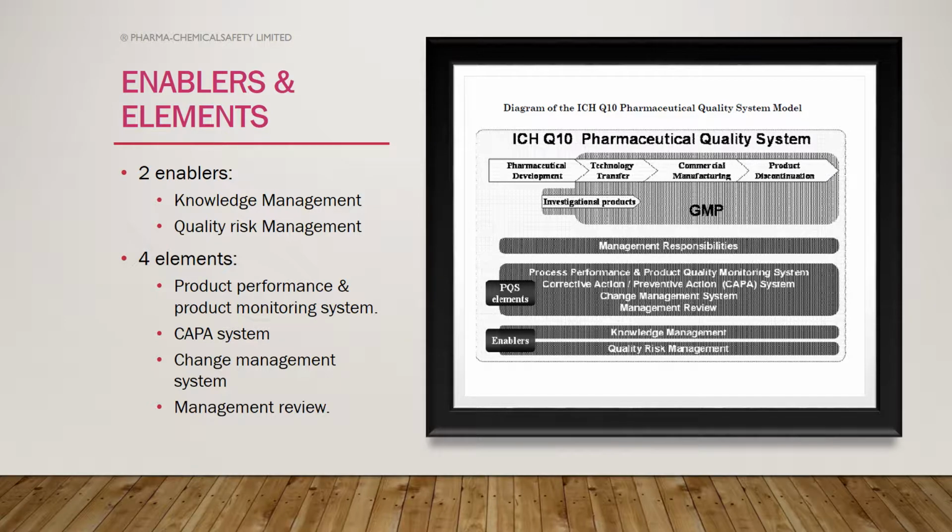Or if during the process the rupture disc is blown out consistently. On that part, actually, you are not maintaining control. So every time you need to write down a deviation, you need to investigate that deviation, and you need to come up with a corrective action and preventive action. That is one element of this standard. And actually, what is CAPA?